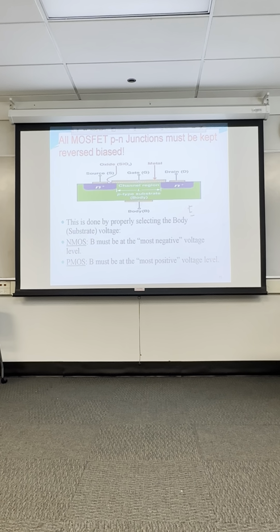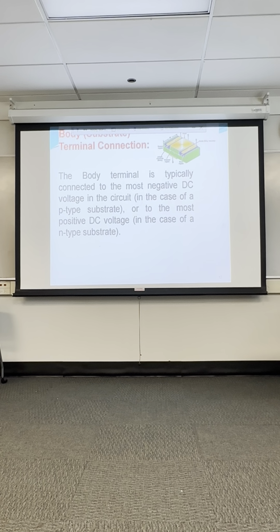This is our gate. So on the icon, we make a little arrow and connect that to the body, and then we connect this to the source. That basically takes care of inadvertently not following these instructions for NMOS and PMOS. That's a creative idea.